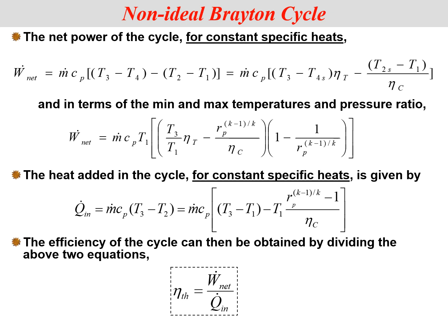This deals with the efficiency, considering we have some mass flow rate as well, because the temperatures and pressure ratios are of course limited, but the mass flow rate determines the overall net amount of work output. Just like this was true for the steam power plant, it is also true for the gas turbine. For example, you solve this cycle for 1 kg of mass moving every second, but then you may have 50 kg per second or 5 grams per second.